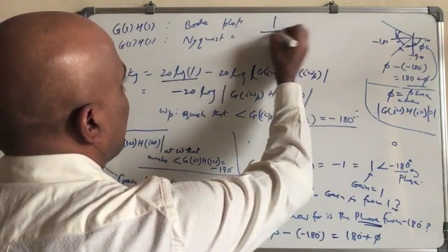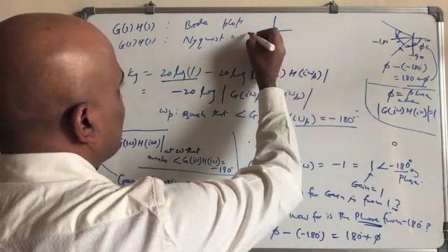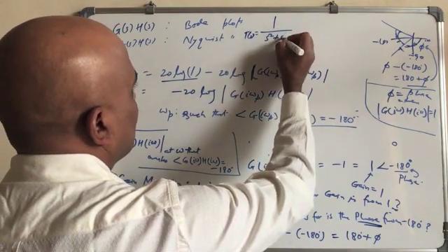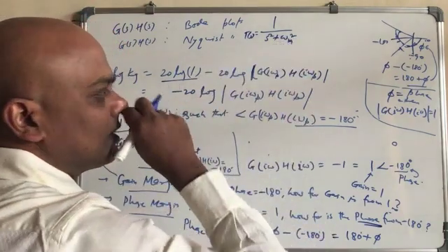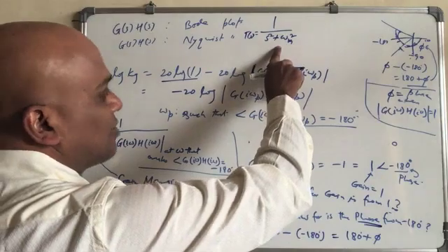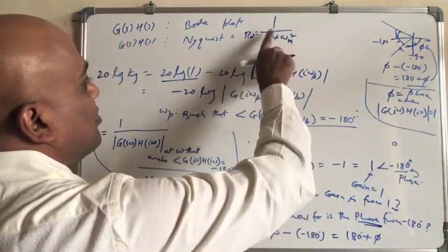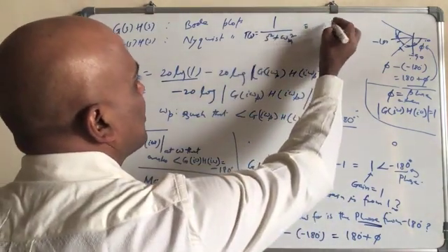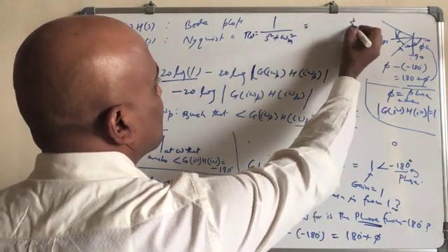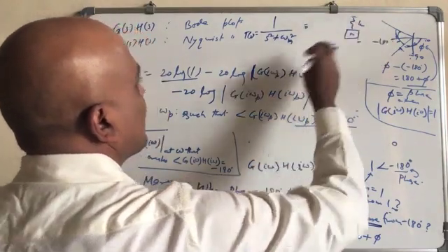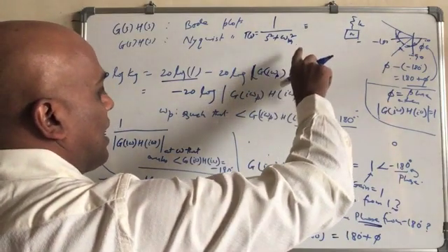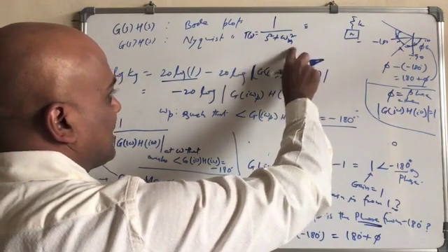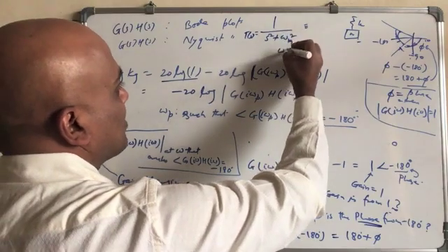For example, remember if you have the transfer function T(s) equal to something like s squared plus omega n squared, you know that zeta equals 0 in this case, and if you take the inverse Laplace transform you will get a sinusoid. This is representative of a spring and mass system. In this case, what do we see? This becomes relevant at omega equal to omega n.